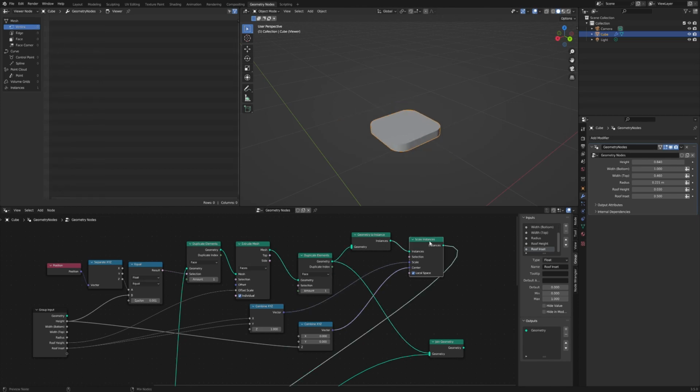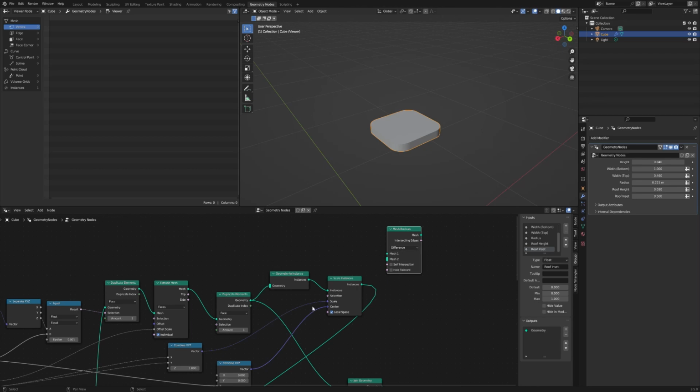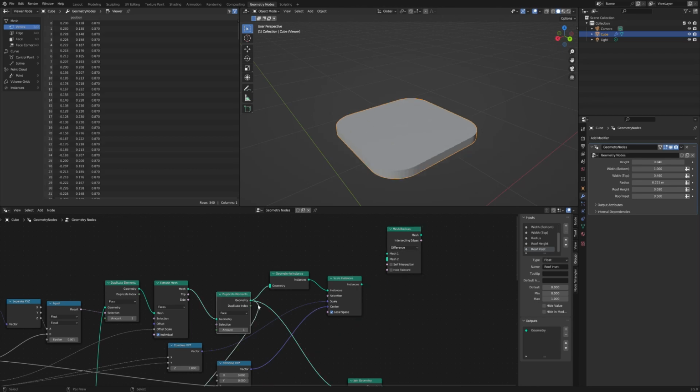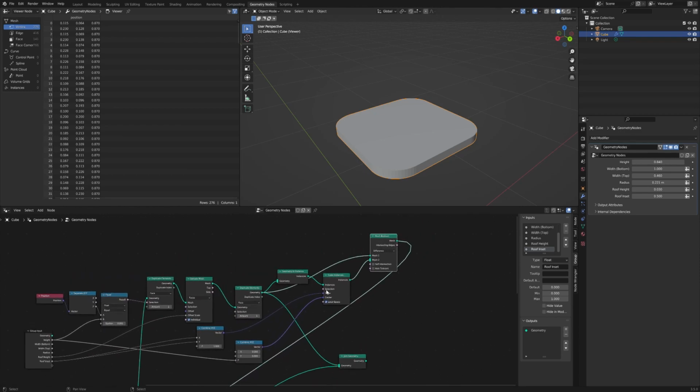So we now have our big shape and what is going to be our inset, and we're going to use that in our Boolean. There's a mesh Boolean operator, and we're going to do the difference. We want the difference of our base shape, which is going to be mesh 1, and then subtract mesh 2. At the moment, you'll notice it doesn't do anything, and the reason is that they're both perfectly the same height.